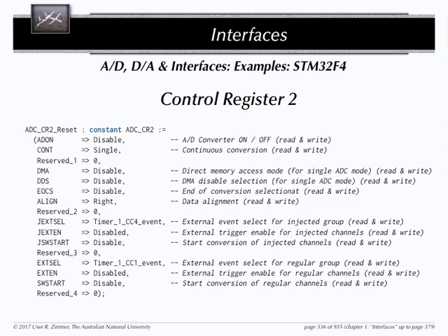You use it to generate interrupts. What is it technically? I give you a bunch of logic, a bunch of electronics. You go to your VHDL programming environment, give me a timer. What do you do? It's a counter. Yeah. It's an independently clocked counter, which runs independent of your main CPU. You can set it to something, and it can do something if a certain count has been reached.